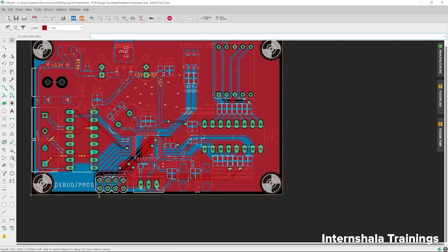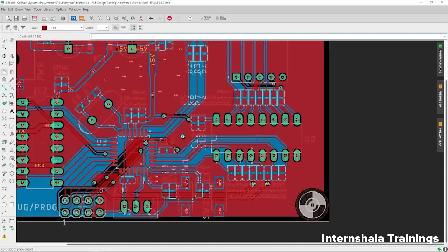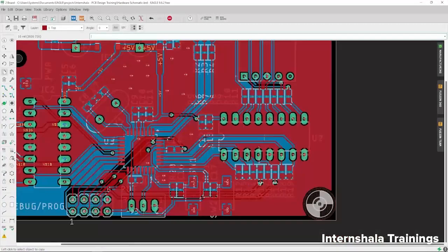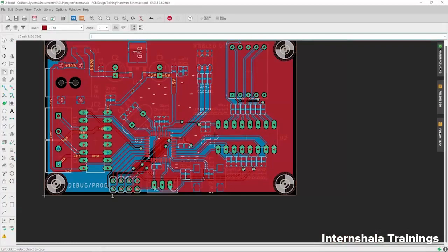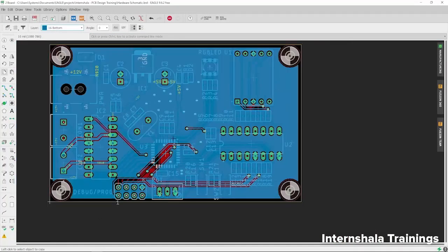Whereas if you had provided a wire at this point, so let's try to provide the wire here. If I provide a wire here, the current is going to flow like this at this point. Then from the bottom layer, from here, it can choose the shortest return path. So with this wire, we provided the shortest return current path to this particular IC.